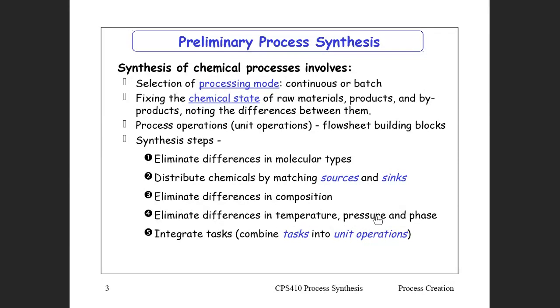So you need to put in a pump. If you need a change of pressure, you can put in a pump, or if it's a vapor, you would need to put in a compressor. And this is something that many students get wrong in the final exam. Recognizing, is it a liquid, is it a vapor? And whether you should put in a pump or a compressor. And those have got different symbols in process flow diagrams.